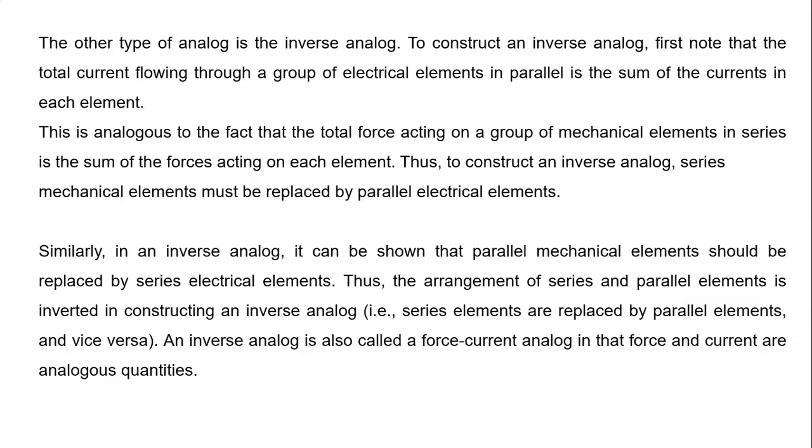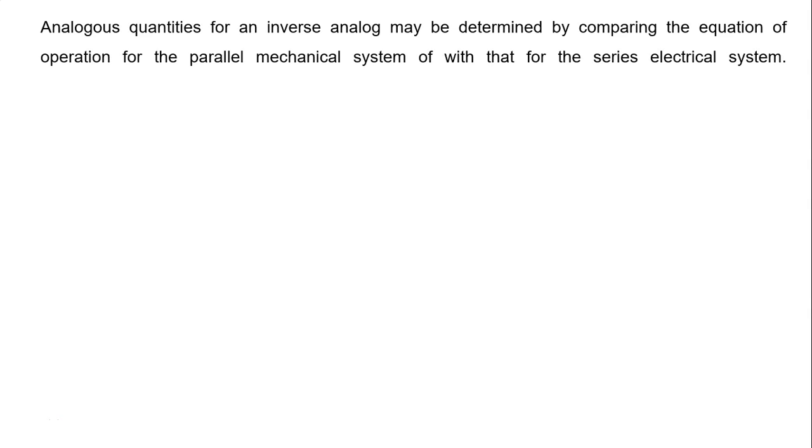An inverse analog is also called a force current analog, in that force and current are analogous quantities. Therefore, now we will see an inverse analog circuit. Analogous quantities for an inverse analog may be determined by comparing the equation of operation for the parallel mechanical system with that for the series electrical system.